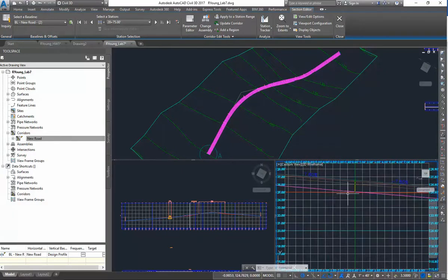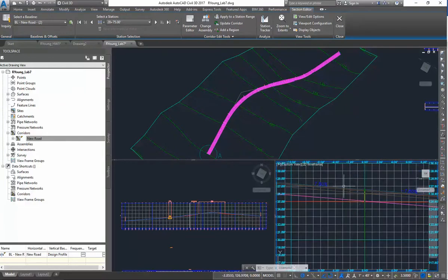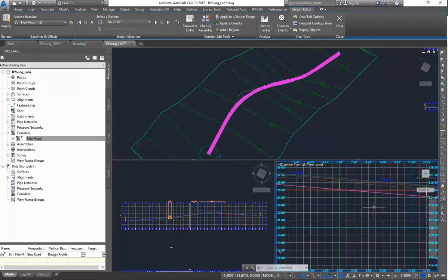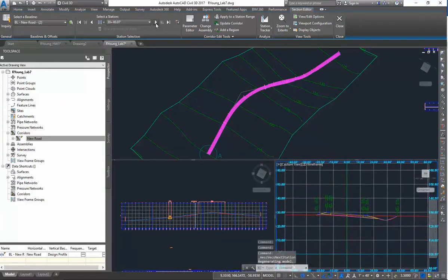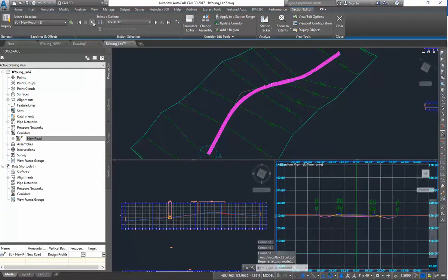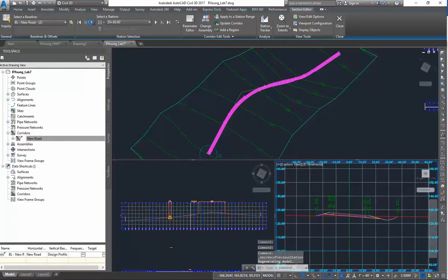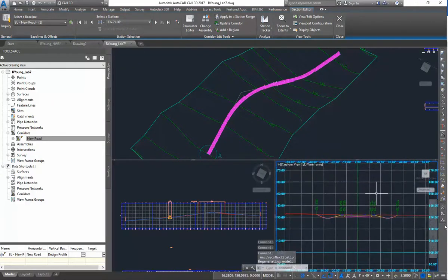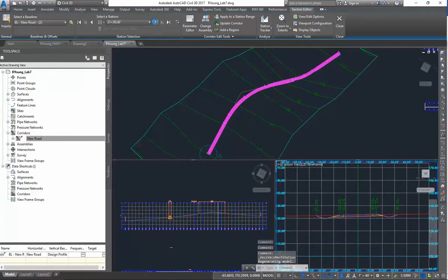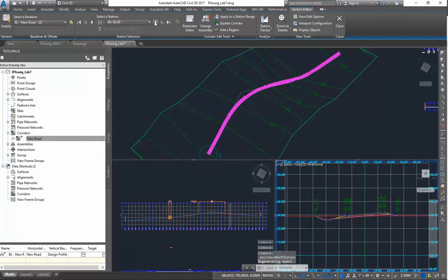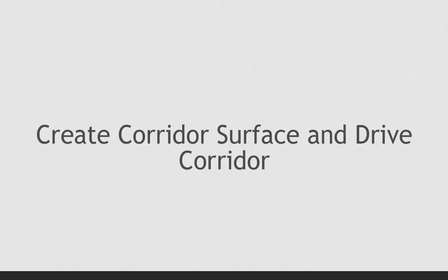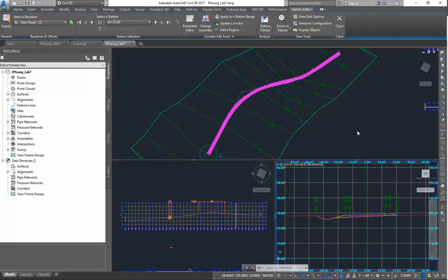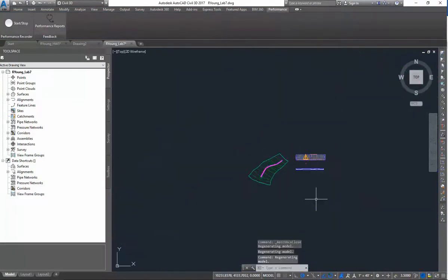The other thing I want to point out is that now I'm in my curve. I'm actually coming out of it. And so you can see how I've super elevated, right? I'm at 7.8, right? And as I kind of move through, it's going to start rotating, right? You saw how that rotated. I'm going to back up just a little bit so you can use this to really view how your road is sort of coming into and out of super elevation. So now I'm back at my 2% crown because I'm on the tangent component of it. And if I kind of move through it, you'll see that I start to rotate the other way. And I'm moving into and out of super elevation. Okay, if I just hit close out of this section, it gets me back to my normal view.